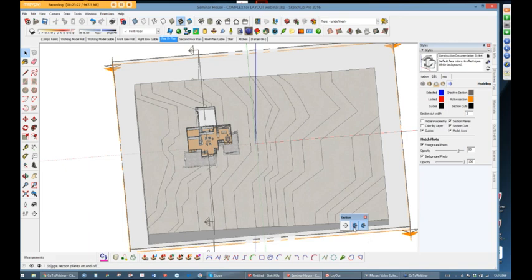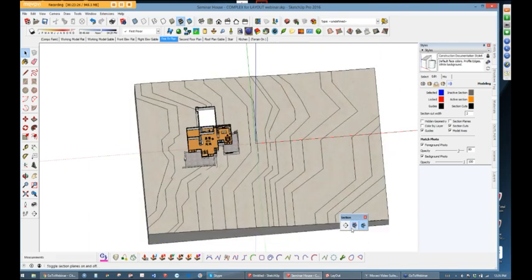So you can see they're there. And if you turn that off, they're going to be gone. That plane just gives you an image of where that cut is. It has nothing to do with the actual cut. And then turn the section cuts off, and you'll see them either show or not show. So floor plans, not elevations, but sections, obviously. Use the section cut tool rather than just looking from the top. I guess that's the whole point of this.